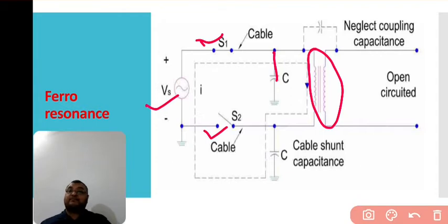exactly focusing ferroresonance in a specific situation is very intricate, because the phenomenon shows a chaotic behavior. Whenever it happens, it shows a very chaotic behavior. The magnetic coupling between the phases in the transformer is one of the key factors regarding the occurrence of ferroresonance.